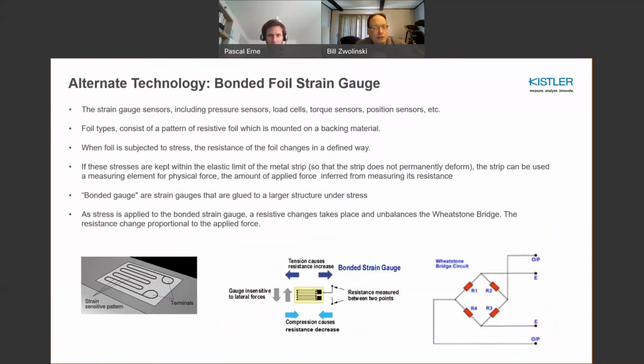We talked about piezoelectrics, where you basically have a very stiff sensor made of quartz and metal, and you're relying upon the forces or the loads on that piezoelectric material, which would be proportional to the measured force. In terms of bonded foil strain gauges, you're using a flexure element, some device that flexes, and you're using a change of resistance, which is proportional to the load. So it's a totally different concept. But what happens is in strain gauge, you're able to measure pure DC, pure static load measurements. So it's absolutely quite optimal for that.